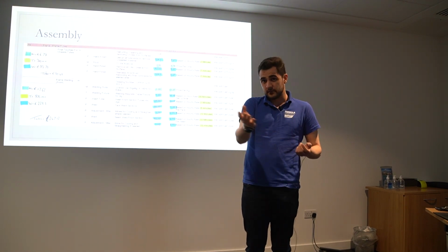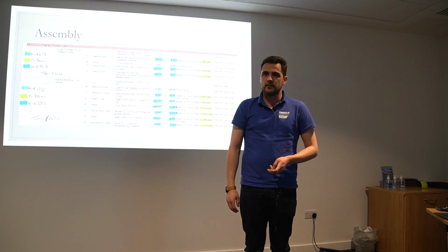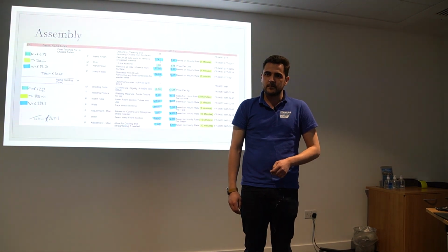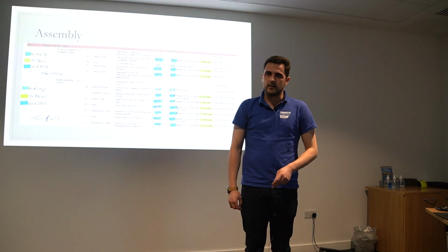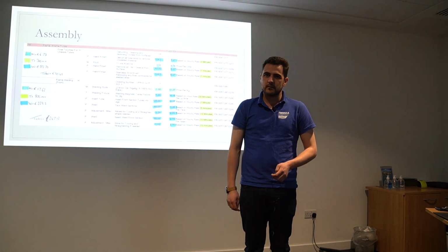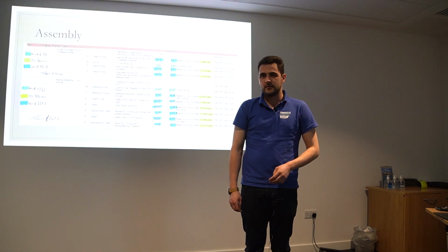Okay, so let's go next. On like the material for the pattern block first, and you have the machine process, machine the pattern block. Yep. Then you make the mold out of the pattern. This is kind of all the tooling stuff. Yeah. Then you go down to the composite level itself. Then again, have the material for the plies, just the carbon fiber. Then have more like the breather layers, the butyl plies, carbon, the nylon layers, and all that stuff. Then have again just all the manual layout processes, debulking, debagging, and then curing time, and then post-processing.